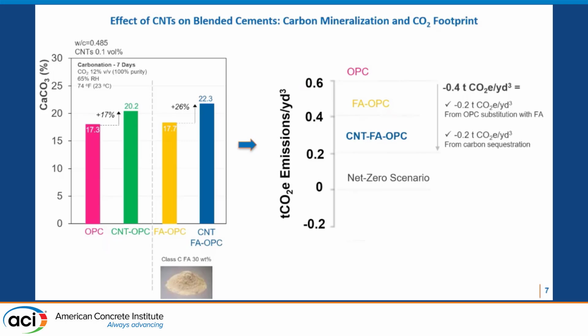So we decided to add one of the recommendations that the cement industry is giving us, adding a little bit of supplementary cementitious materials, fly ash, in the system, and this is fly ash class C. The reason that we wanted to use specifically class C is because we wanted to add a little bit of calcium. We did not want the pozzolanic reaction to take up all the calcium, and we wanted the mineralization process to increase.